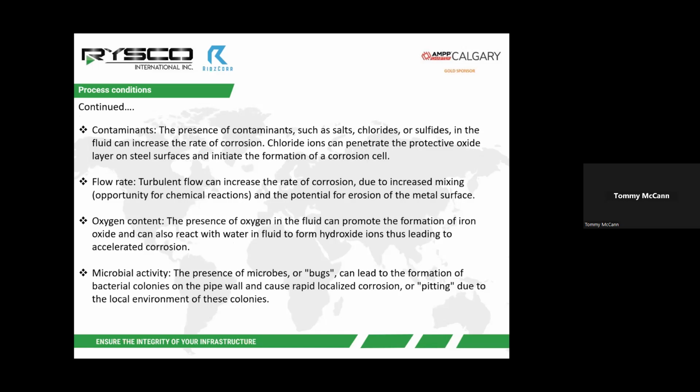Contaminants, so very commonly things like salts or chloride, sulfides. When these are present within the fluid, you can see, for example, situations where the chloride ions can penetrate your oxide layers, and almost initiate a corrosion cell.